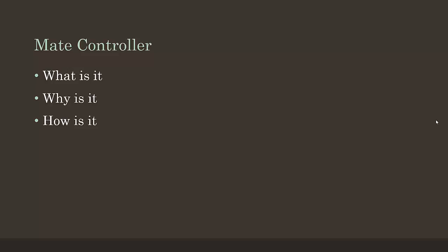Oh, that's right. eDrawings can support it in 2017. I forgot about that. Yeah. So you can animate that, save it as configurations, and send it to your customer, and then they can watch the animations through eDrawings. So, that's a good one.